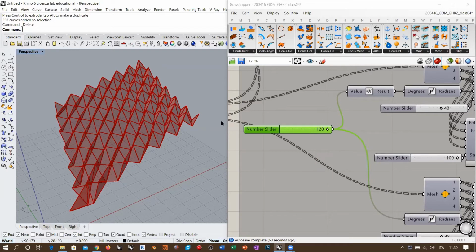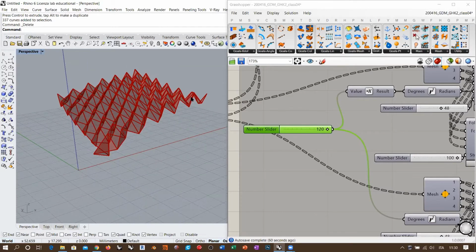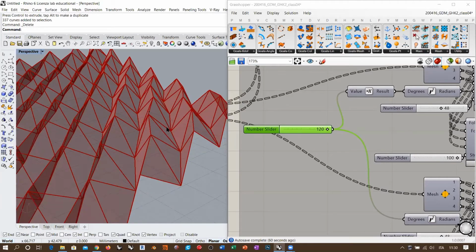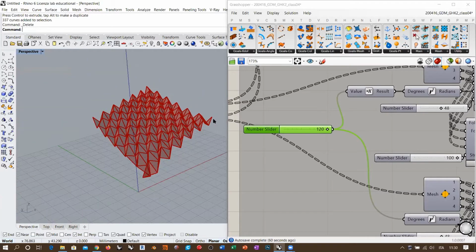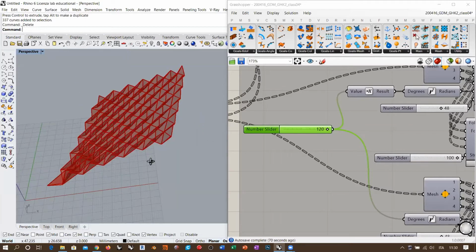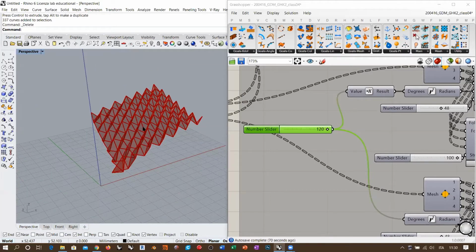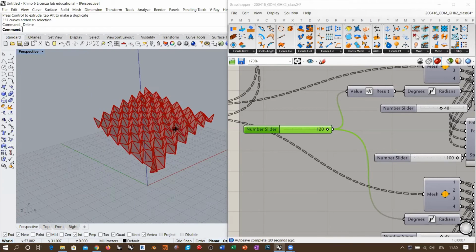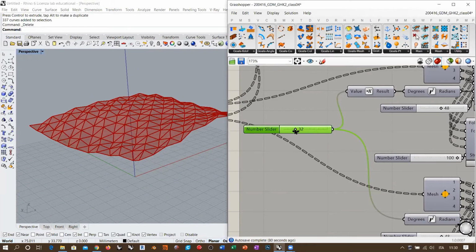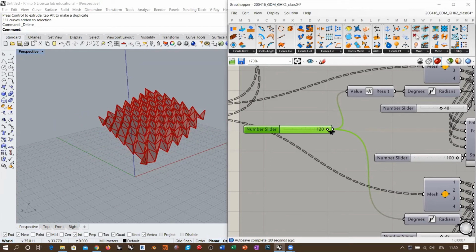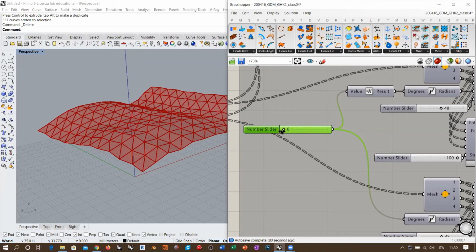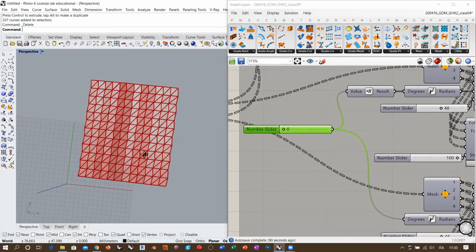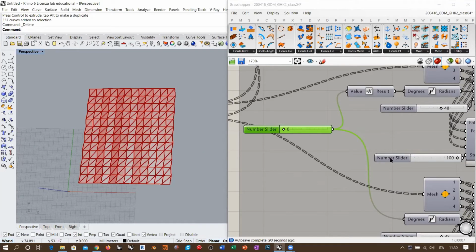Also because when you try to fabricate or produce this, you are not going to work with materials that have zero thickness. So you cannot simply pack this totally with 180 degrees into one single flat surface. Okay, there will always be a thickness that you must take into account. So don't ever exaggerate with this angle. Once you have the right behavior happening, you know that if you increase this angle, you will get a more compact packing. But the important thing is to double check that the origami is behaving properly.